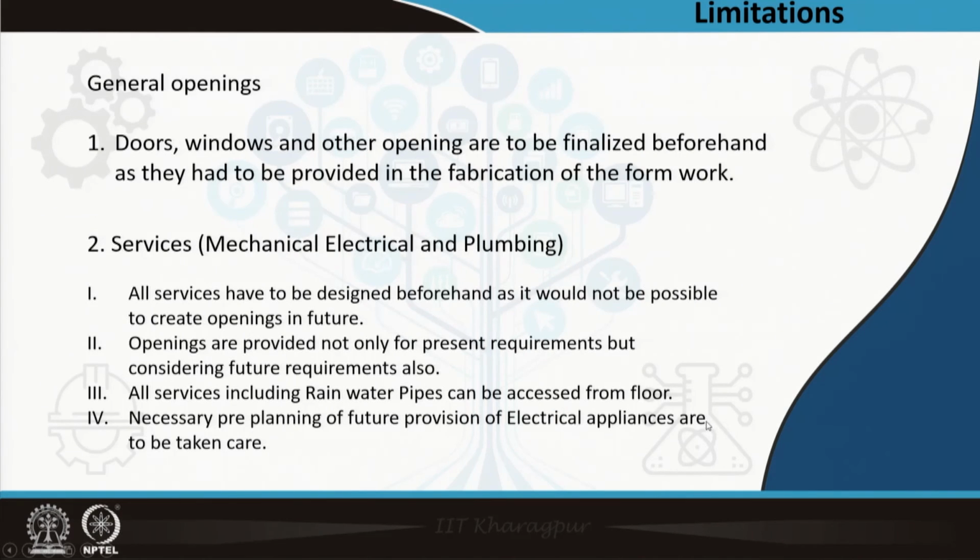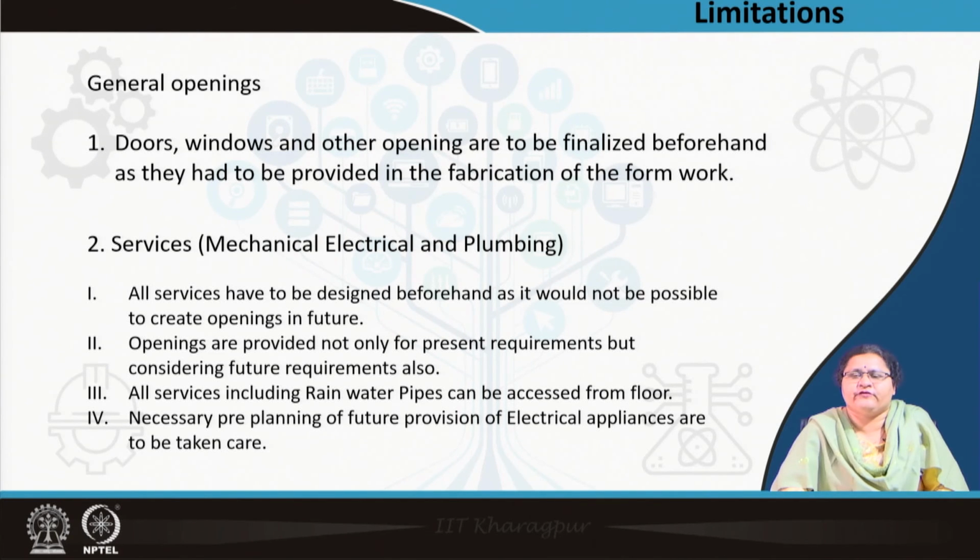Now, coming to the general observations, it is particularly the openings. I told you, you have to finalize them beforehand. You have to give them during fabrication and you have to know which place they will come. So, a proper understanding of how to organize the systems into a building built form is to be known. Doors, windows, other openings should be marked.